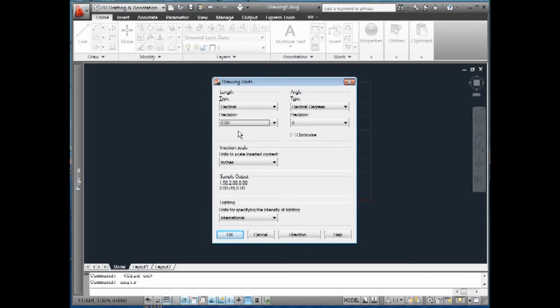That'll be good enough to start drawing. Degrees and decimals. This will show us 45 degrees, 30 degrees, 15 degrees. If I wanted to show us a fraction of a degree, I would just change that to show the precision at 2 decimal places or 1/100ths.